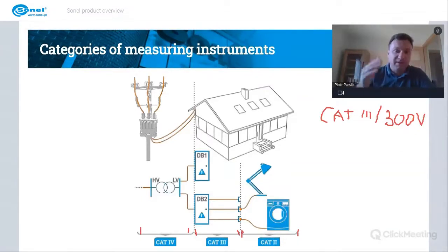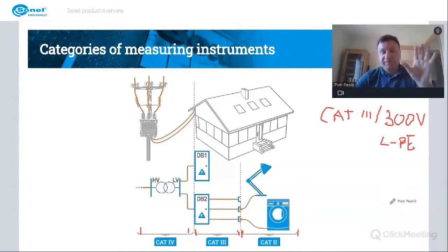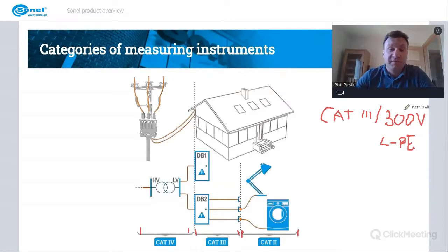There's 400 volts and this is only marked 300 for safety. Well, yes, because the voltage stated in the measurement category refers to phase to ground voltage. So when we have a system with 230 phase to ground and 400 between the phases, we can use a meter with safety marked as 300 volts, because phase to ground we have only 230 and not 300.